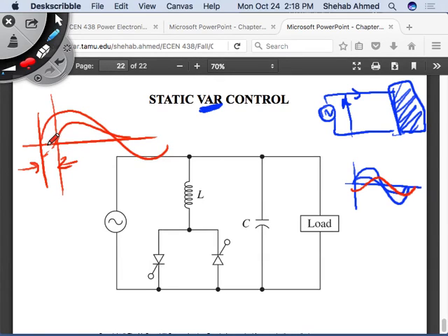They don't charge the home consumers for the reactive power, but of course they enforce rules on industrial consumers so that they stay within a certain limit, because what they charge for is the active power, right? If they allow you to draw as much reactive power as you want, and they don't charge for it, then they're losing money, right? And they are buying equipment that is rated to a very large rating, and this rating depends on active and reactive power going through it. So they're not charging you for the equipment, they're not charging you for the power, then there's disaster for them, right? So they force you to operate within a certain power factor.